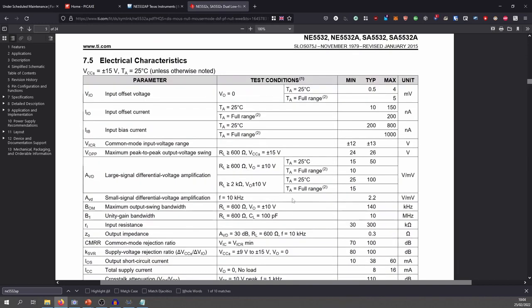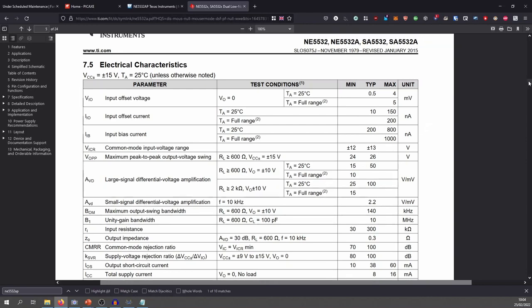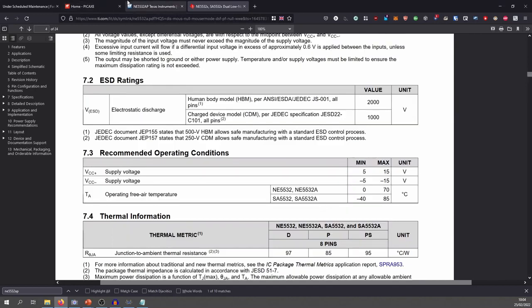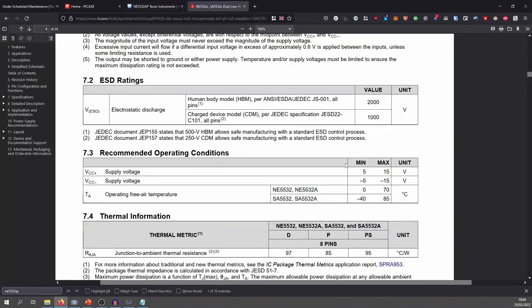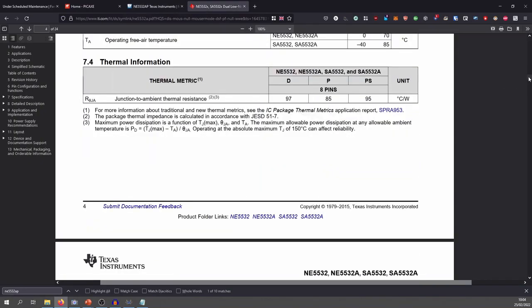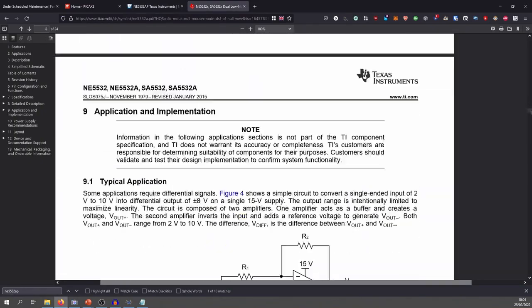Right, so let's quickly check the pins, which should be pretty straightforward to do on this one. When you're inputting, you know those 8 megahertz figures that I put into the library, you want to check that that's actually the case in the datasheet. What I'm saying is don't trust this information here. All distributors get that wrong. You have to go into the datasheet and check the component itself. That can be used as a rough guide. This is where you'll actually find your information. Needed to get that off my chest.